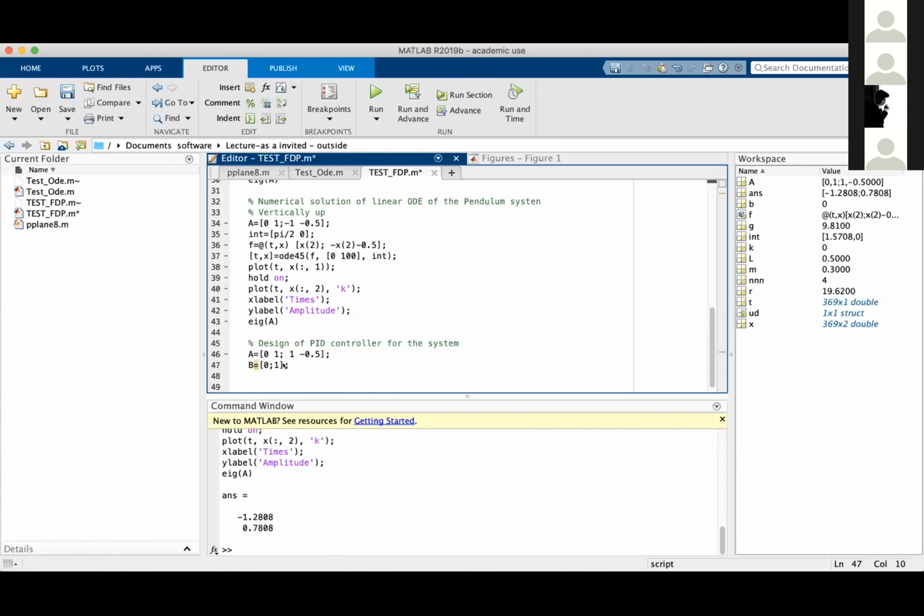And the only state we want to measure is x1. If you remember the state space representation, x dot equal to Ax plus Bu, y equal to Cx, and C determines which states you are looking at. You want to look at the output terminal basically.